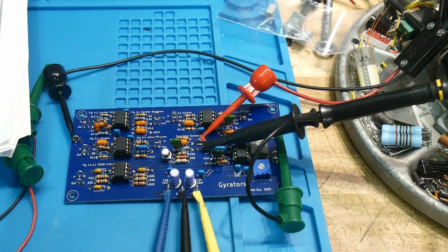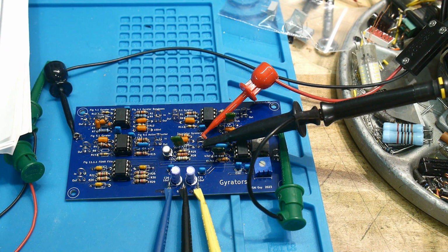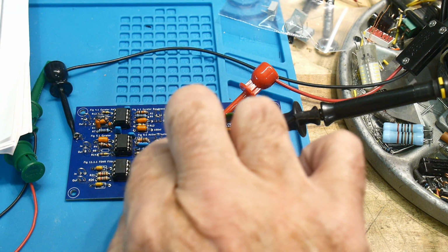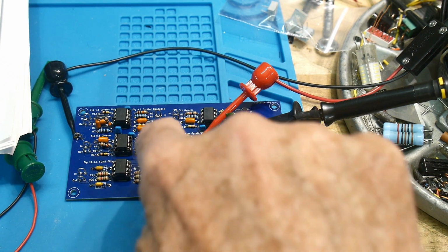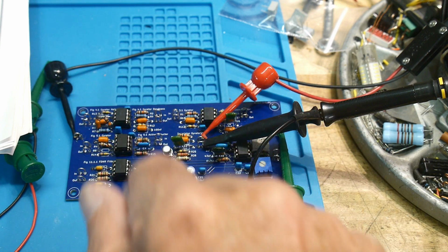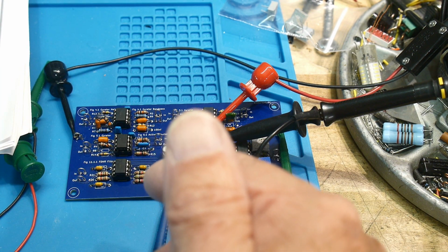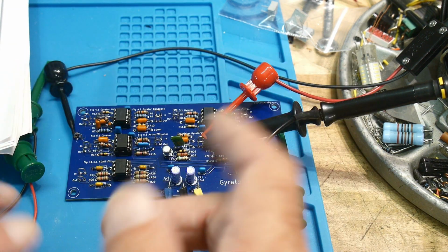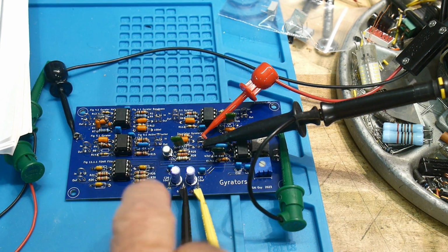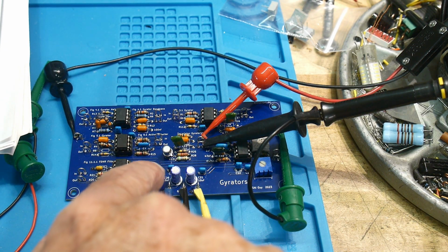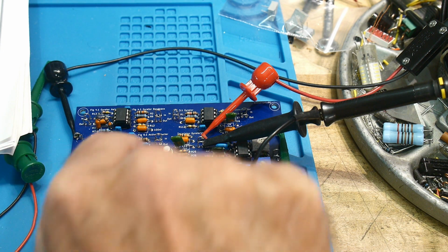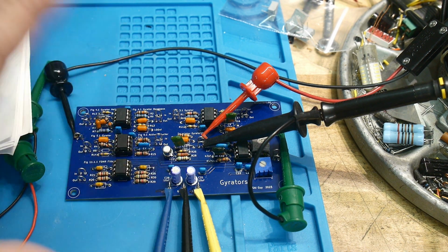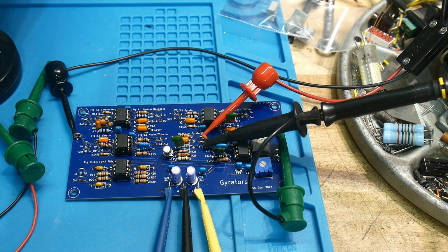If you get one of these boards, be aware that the pinout of TO92 packages is not standard. And so this one is laid out for a 2N2222, which is, the tab is emitter-base-collector. A 3904 is the other way around, so be aware that there's no standard for these. So if you try to use a 3904, be attentive of where the emitter, base and collector go onto the PC board, because the artwork will mislead you if you're not using a 2222. All right, let's look at the next circuit here.